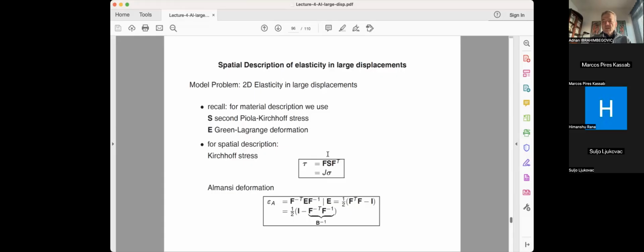So please recall, tau is a stress tensor which is acting in the deformed configuration, contrary to the second Piola-Kirchhoff stress, which is acting in the initial configuration and is parameterized with the coordinates in the initial configuration. That's why you have to have this motion phi all the time, so you can establish a connection between those two configurations. So I'm still taking the Lagrangian formulation, but the objects I'm using are not necessarily those sitting in the initial configuration. This is just fine as long as I'm using coordinates in the initial configuration. The computation is just repackaging these objects and nothing else.